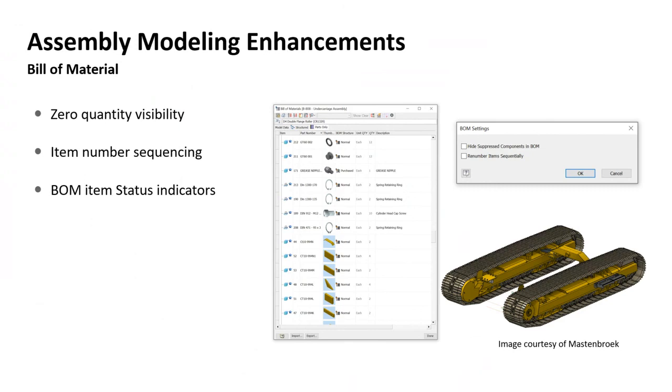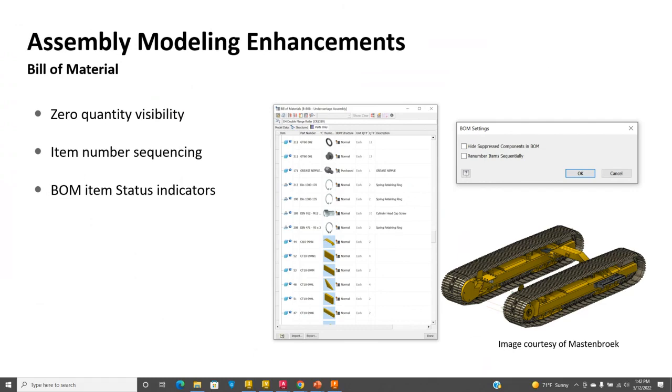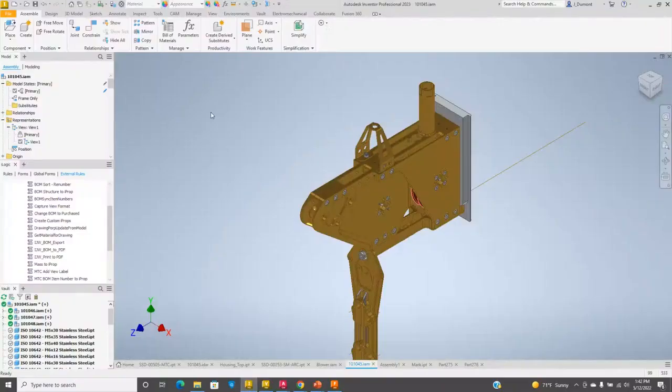Okay, so for assemblies, those of you who have not used them yet, model states are kind of a big deal. For those of you that have not used them, most likely you're doing iParts or iAssemblies. So they're not replaced with model states. This is new technology that runs parallel. You have a choice to use either or. I'm not going to get into model states today because they're not new. They came out in 22, but they did add some functionality.